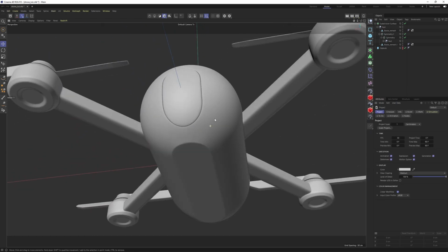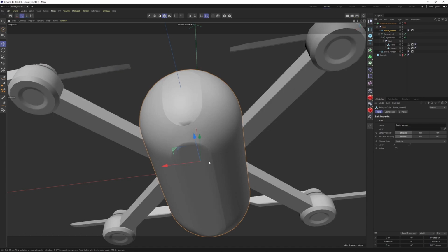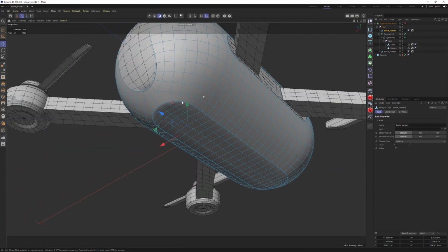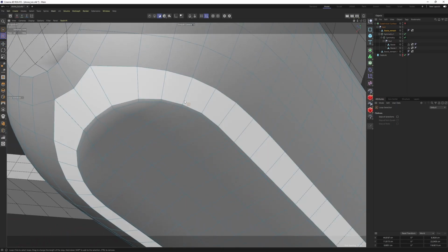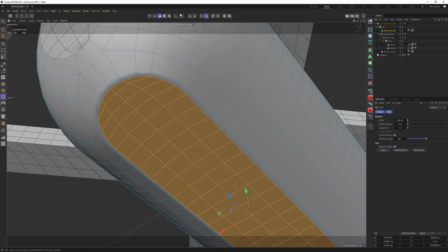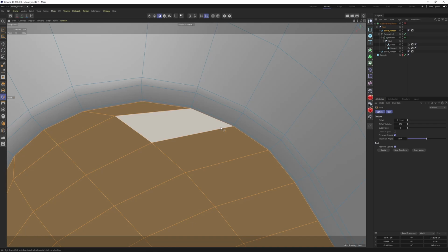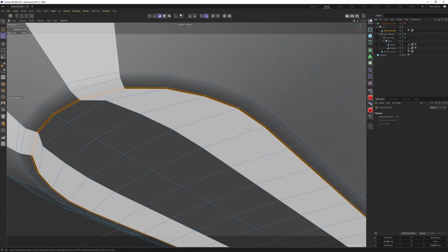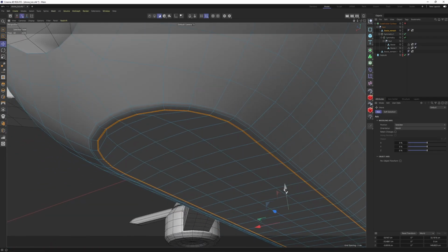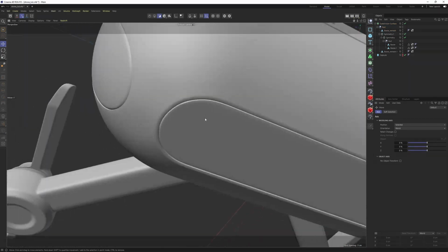Now let's check the bottom part because I want to add more details to that part. Find the mesh. Switch to polygon mode. First, let's create some panel loops by insetting these polygons over here. Then I'm going to do that one more time. Then make a loop selection, select this new polygon loop, hold down control, move these twice, hit Q.